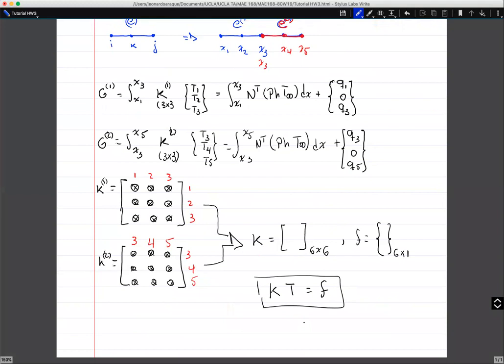So now I can go to the force vector, and at the corresponding node or degree of freedom, I can impose the boundary condition if there is any. All right? Which is for the last node in our element, which is at the position x5, we have a natural boundary condition. So we need to make the substitution on that forcing vector at that node, for that boundary condition.